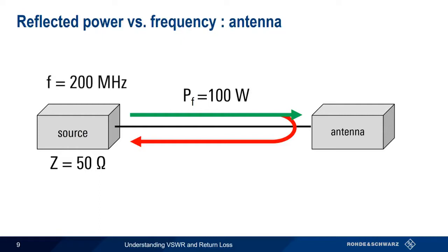At 200 MHz, the level of reflected power goes down to less than 1 watt. But at 500 MHz, the level of reflected power is now 25 watts and increases to 50 watts at a gigahertz. Most real-world devices fall somewhere in between these two somewhat extreme cases of little impedance variation by frequency and large or irregular impedance variation by frequency.